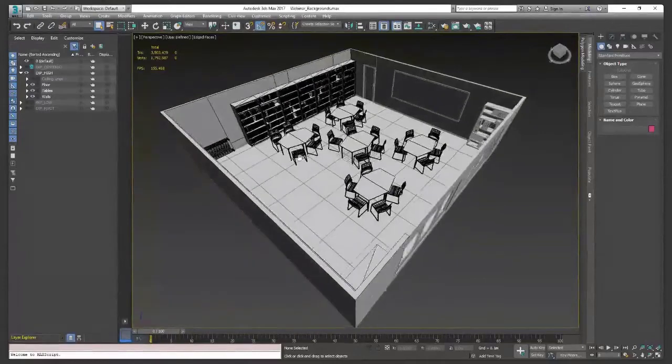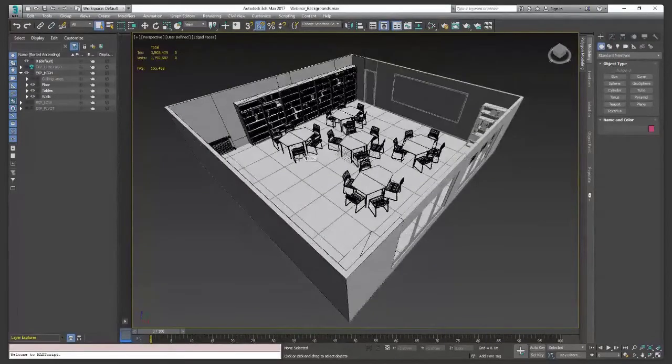However, when we talk about real time in Anima, we have to take into account how Anima works. Anima in real time doesn't calculate just the render of the model in the viewport; you have to consider that when importing the model it also calculates the collisions, and the collisions are those then used by the real-time simulation elements we use in Anima. So one important thing is to keep the detail down.